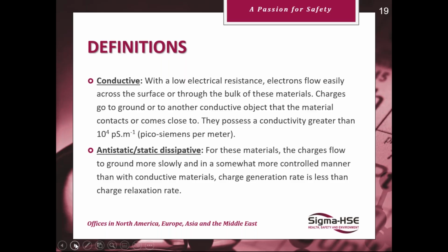And this is how your shoes work, your floor, etc. It's static dissipative rather than conductive. If you had a conductive floor and conductive shoes and you got static blown through, you could get a very bad shock with it. So having it controlled in its release is better in those types of instances.